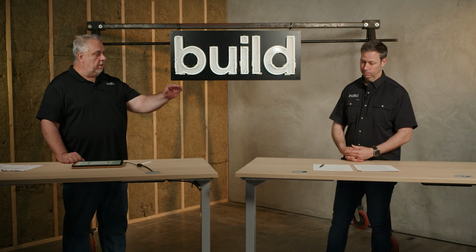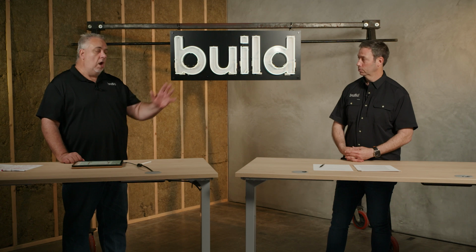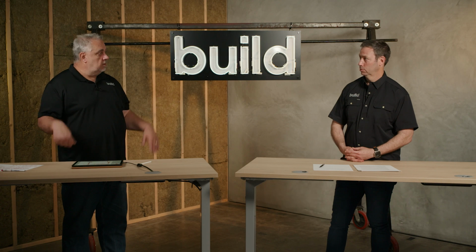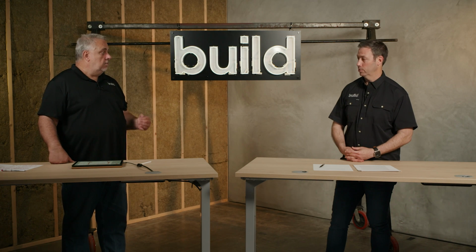And the thing about airtightness is that probably the first 30 or 40% of airtightness management is low-hanging fruit. It's just a very slight conscious effort to that building assembly. Hey, seal this joint. Hey, run a bead of sealant along here, or run some tape across this joint in our project there. And that number goes crazy good. Yeah, it gets better.